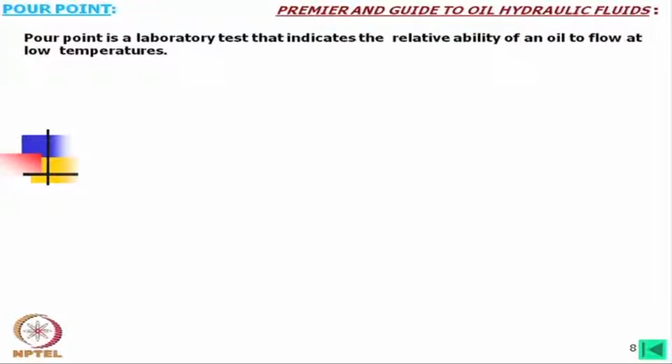This is important mainly where the operation is being held at very cold temperatures, say during winter in some European or northern countries, where pour point is very important. So, we have to take oil of a lower pour point for those applications. On the other hand, in hot countries like India and other places, we need not take care of the pour point so much.